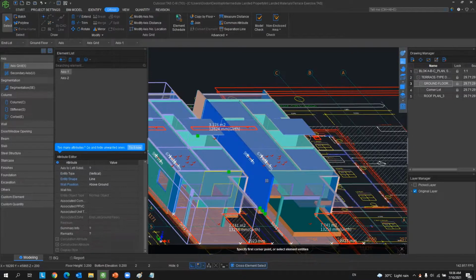For all the elements, if you have this all shed, you need to put the remarks as a shed. So later on, when we get the quantity, we can classify it by the remarks, and then we can see which one is the full, which one is a shed one. So for the shed, the quantity you will need to divide by 2.